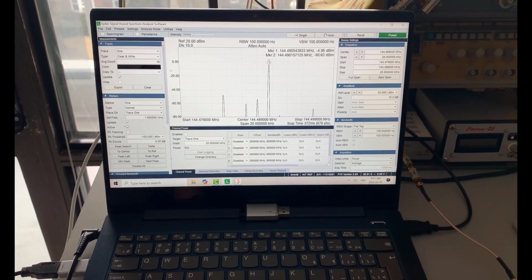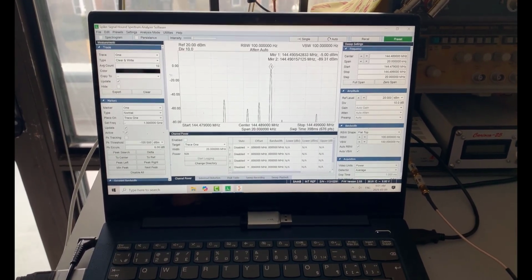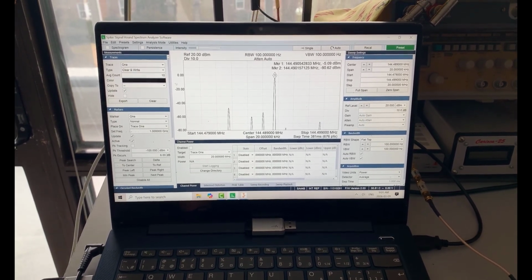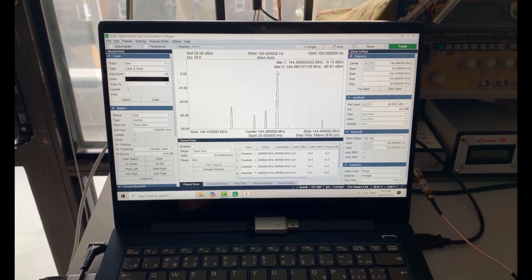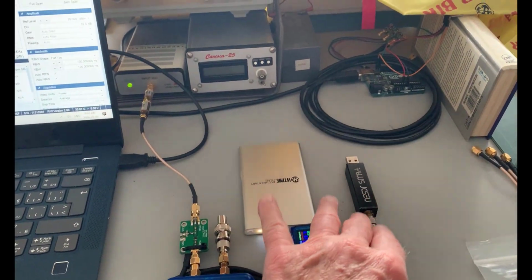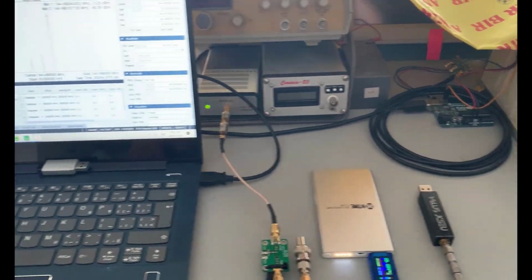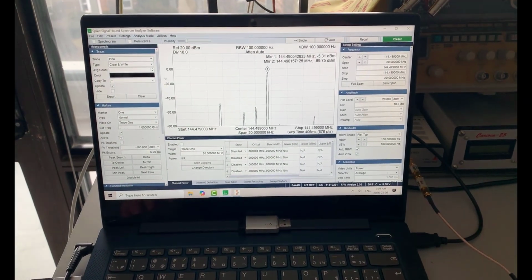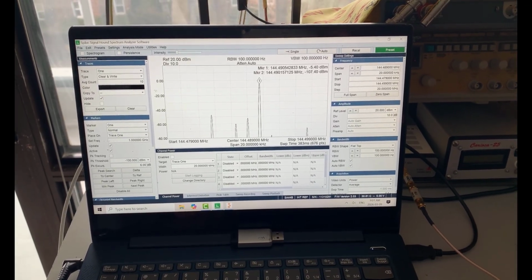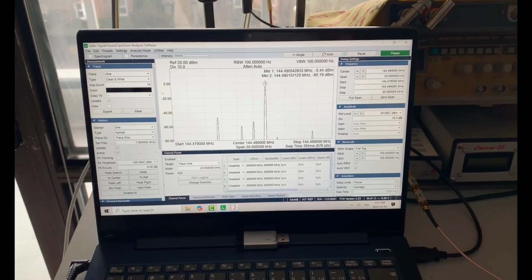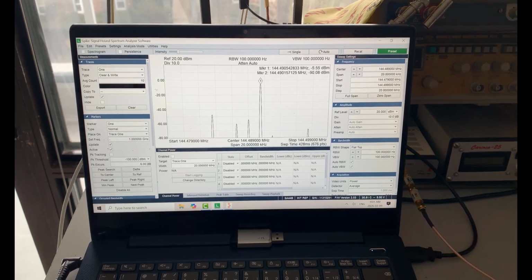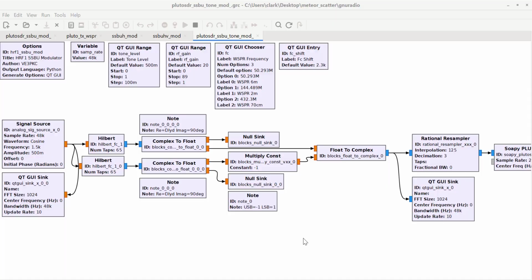I find that with the Pluto, you've got to be careful not to overload it. So the audio signal coming out of Whisper, you have to look at the volume carefully so as not to overload the transmitter. Also, I'm going to do a loopback test. I've got an RTL here, and I'm going to feed that in. On a separate instance, I'm going to have Ubuntu running on VMware on the same laptop, and I'll have another instance of WSJT in receive mode working in Ubuntu, so we can do a loopback test. Anyways, we'll look at that on Camtasia.